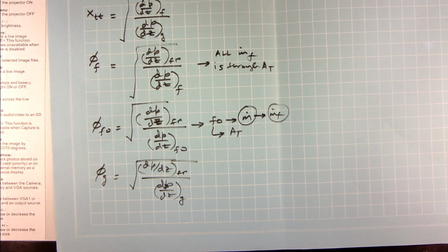Because at the end of the day I do not know what the void fraction is at a particular location, isn't it? Okay. So not knowing what the value of void fraction is, if I can just assume that all of that flow, instead of flowing through a smaller area because of a void fraction being present, if it were to flow through the whole cross section of the pipe, that is easy to calculate, isn't it?